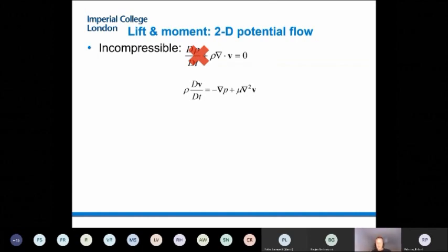The second assumption we'll make, and again, this is relevant for the problems we have in mind, is that the viscous terms that appear in the momentum equation are dominant in the boundary layer. When you look into the physics of this problem, they become the most important when you're looking very near the walls of the body.